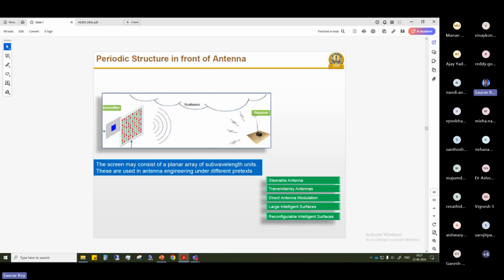So yeah, this is the whole block diagram. What it shows is a transmitter antenna at the blue side, which let's say is a patch antenna. Okay. In front of the patch antenna, we have a metasurface or FSS, which is controllable. These yellow, green, and red things you see are multiple switches, which are controlled through a circuit.